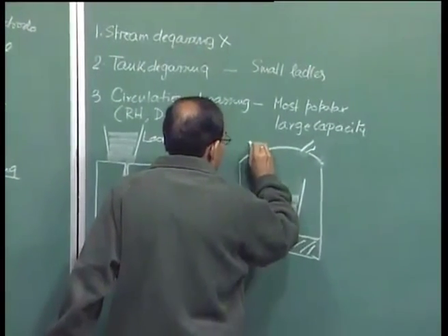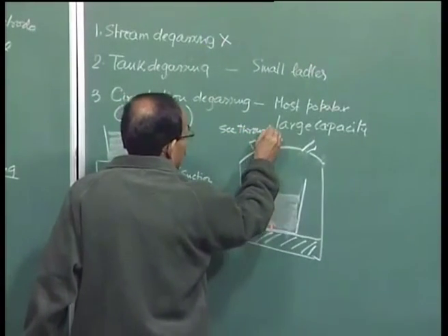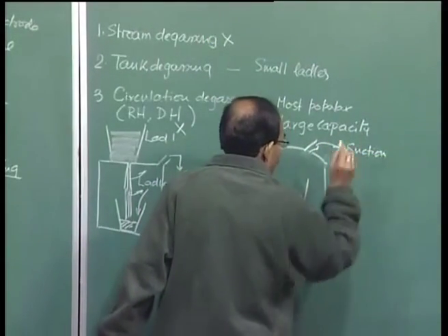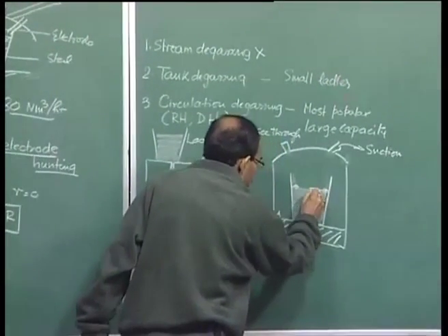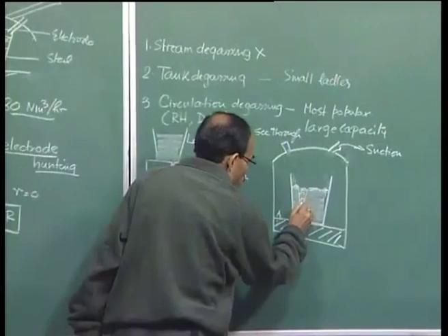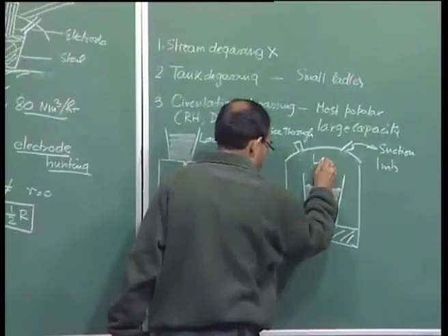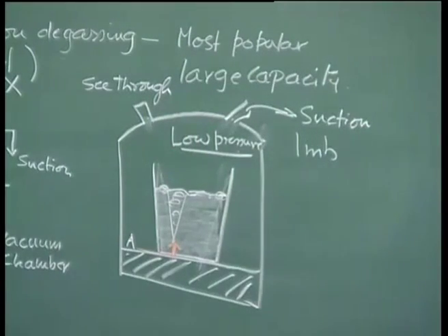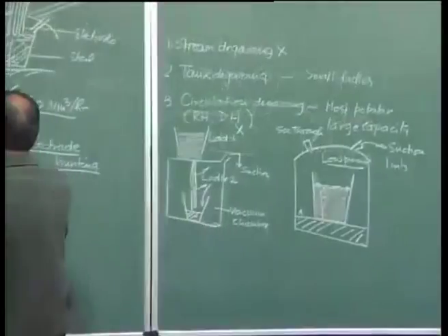we may have some windows also through which one can see what the state is, and then we have suction here, argon is injected here, we have slag here, and the plume is generated, and this produces a low pressure system, and as a result of which fresh material is going to be exposed to the low pressure, and there this particular reaction is going to be facilitated.